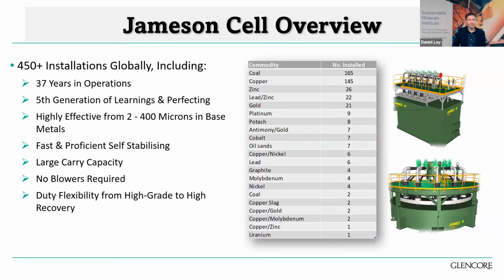They can also be operated very flexibly, either as a high-grade unit with very deep froths and high wash water, or they can be operated more aggressively with shallow froths and very high air to pulp ratios, resulting in high recoveries.